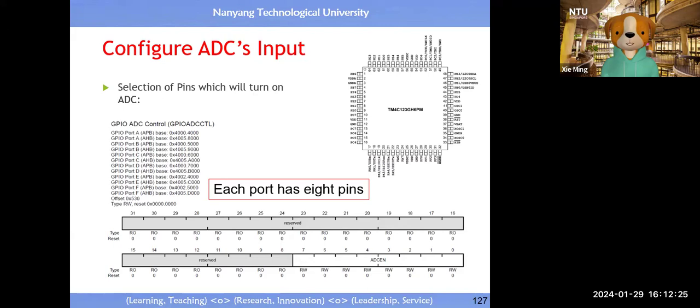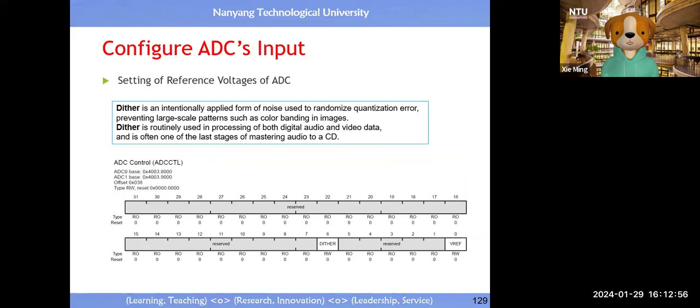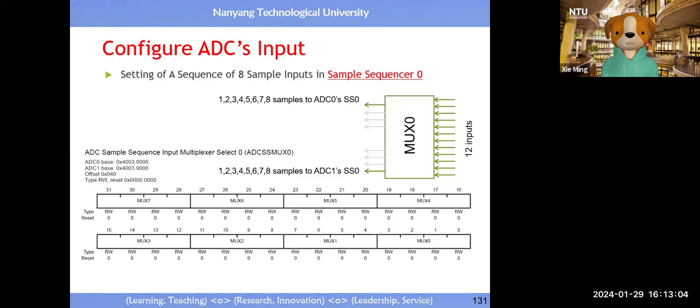Among all these 12 sensors, eventually you can decide whether you want to do analog to digital conversion, right? Maybe some sensors may not use it, depending on the application. So you turn on these ADCs. Once you turn on, the voltage will be input. You see, you will enable. So, ADC enable. For details, you read the instruction, right? And the reference voltage, you just turn it on by setting it to 1, which means it's always 3.3, right? Okay, not much.